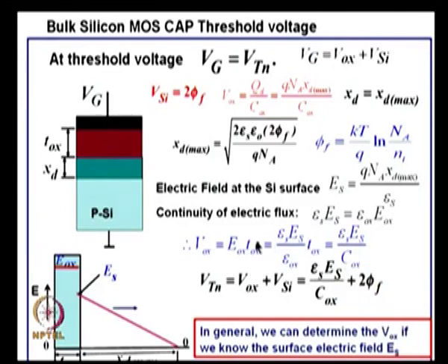That into T oxide gives me the voltage drop. So, what is this quantity? E of s into epsilon s here. E of s is Q D by epsilon s. Charge beyond that surface, whatever charge is there, divided by epsilon s is the peak field. Okay. So, E of s into epsilon s was the charge here. That is the charge. So, the same relationship we got differently.